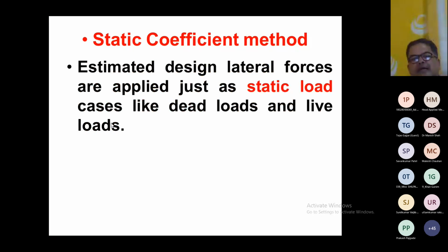This static coefficient method is used to determine the lateral force because of the earthquake. And you see, the name is static coefficient method. It means the earthquake force, basically, is dynamic in nature, but we are applying it in a static way, right? The way in which dead load is acting, the same way we are applying this load, right? So this is not the real condition; the load is actually dynamic. Earthquake load is a dynamic load, but here we are applying it in a static way, right?